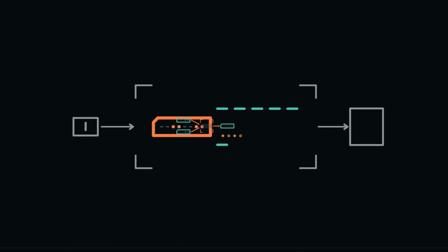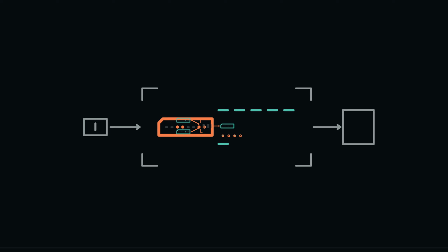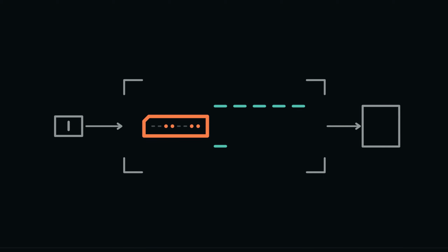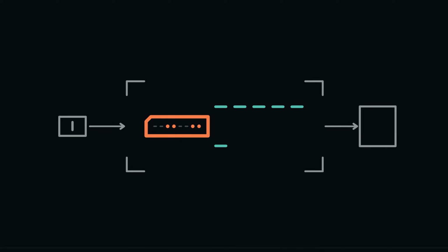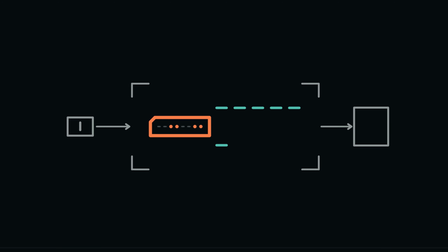Rather than build a separate destination path for every operation, we can place these function lanes behind a selector. Their shared boundary will become the arithmetic and logic unit, or ALU. Keep the 2 operand registers at the entrance and arrange the certified operation lanes without moving their identities: addition and subtraction, bitwise logic, shifts, not, and comparison. Each lane receives the operand bits appropriate to its rule. A compact operation field controls a selector at the far side.